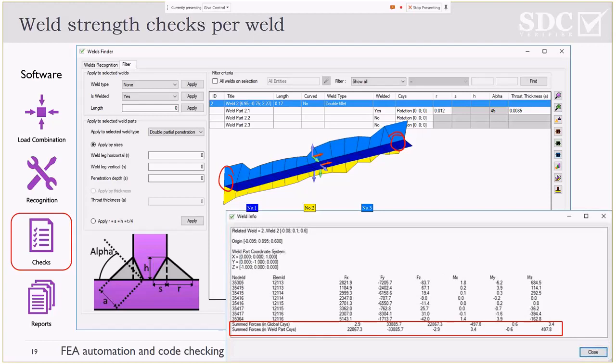That's what you see here. The total forces over the weld in the three different directions, including the moments, are divided by the total capacity of the weld. So in this case, you can save considerably on the total A height. FEA engineers tend to say the A height is always half the plate thickness, but that is a hugely conservative approach.